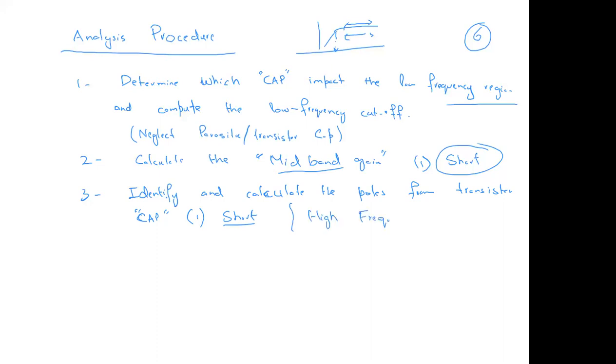When we have all the pole information, we will use the Bode plot to plot. But first, we'll get this information, and those capacitances which are, for example, in this configuration, in the middle of two nodes, we'll use the Miller capacitance to convert into a node and a ground.